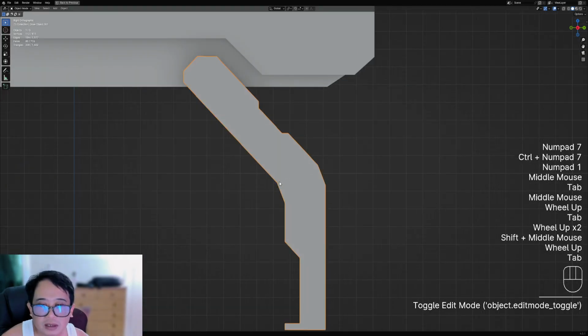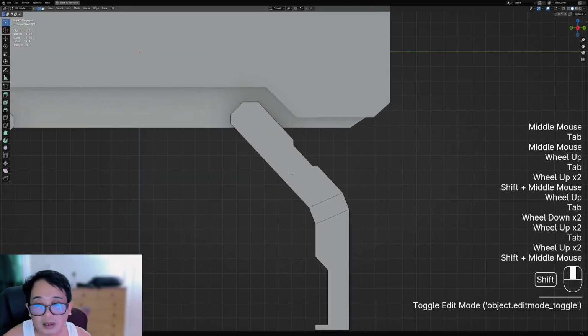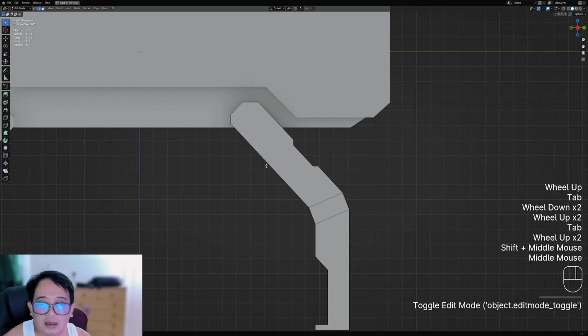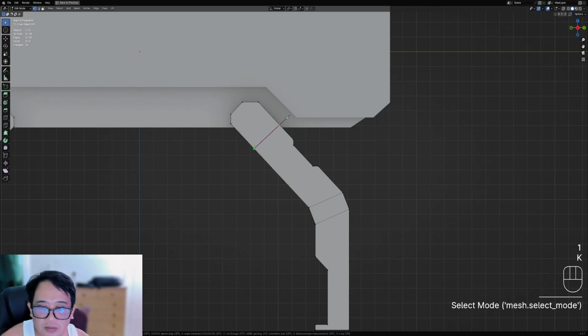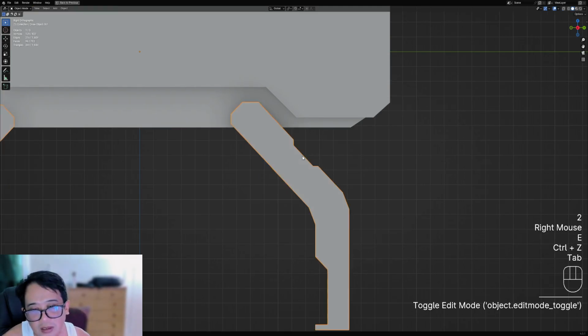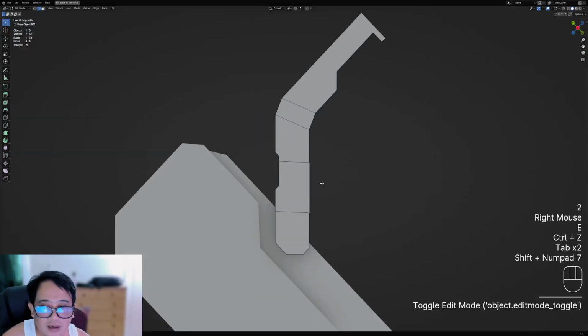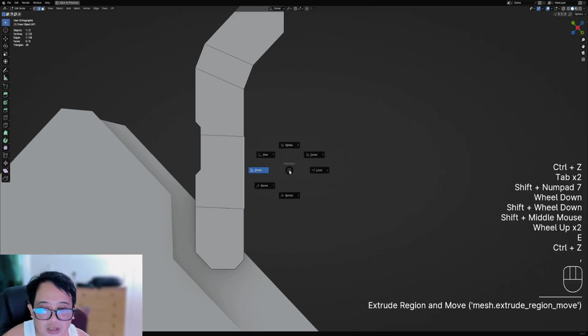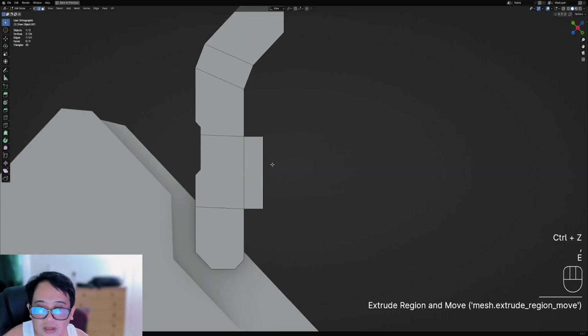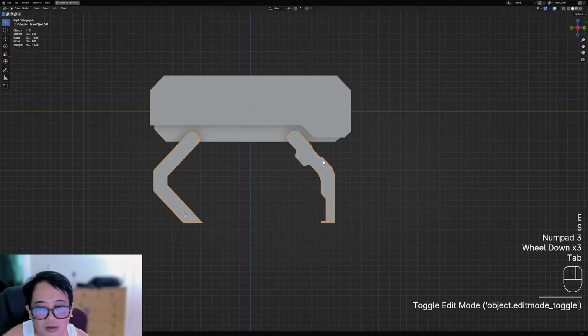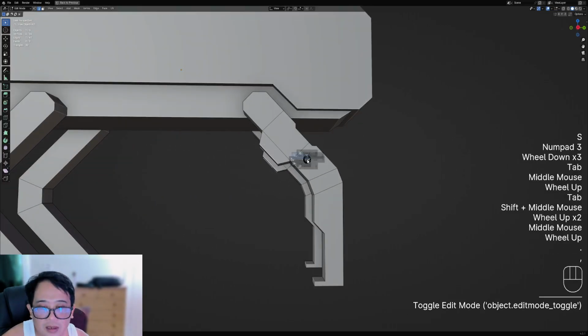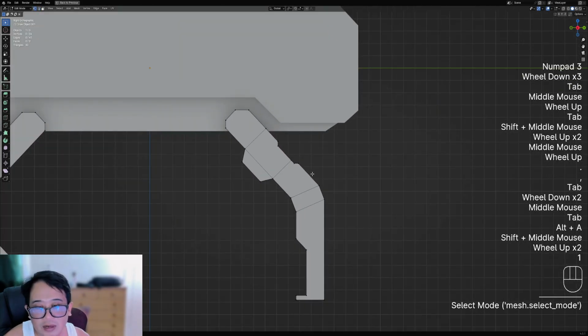Then we need to design something on the inside. Can we add something here? So this is the subtractive method. If we need to add something on the shape, we can create supporting vertices. So we can use Shift 7 on the numpad to bring it like that, and then we're going to change the transform orientation to view. So it goes that way, and 3 again to repair the face, and set this back to global. That's how you can create those shapes.